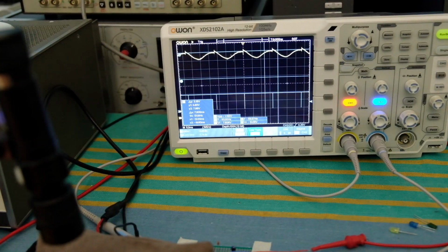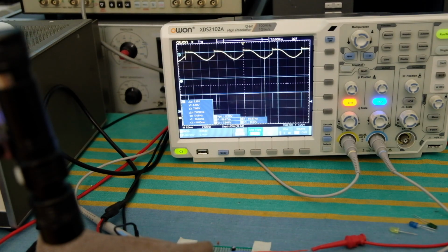So here's the white or UV LED. I guess it's one of the extremely high band gap type LEDs, and you can see I have put in the minimum capacitor of 30 pF. There's already some parasitic capacitance on the NMOS device of around 30 to 60 picofarad, I believe, and that's going to add to this capacitance and effectively increase the cap on that integration node. But you can see the effect of lighting and leakage or other AC hum showing up on this signal now.